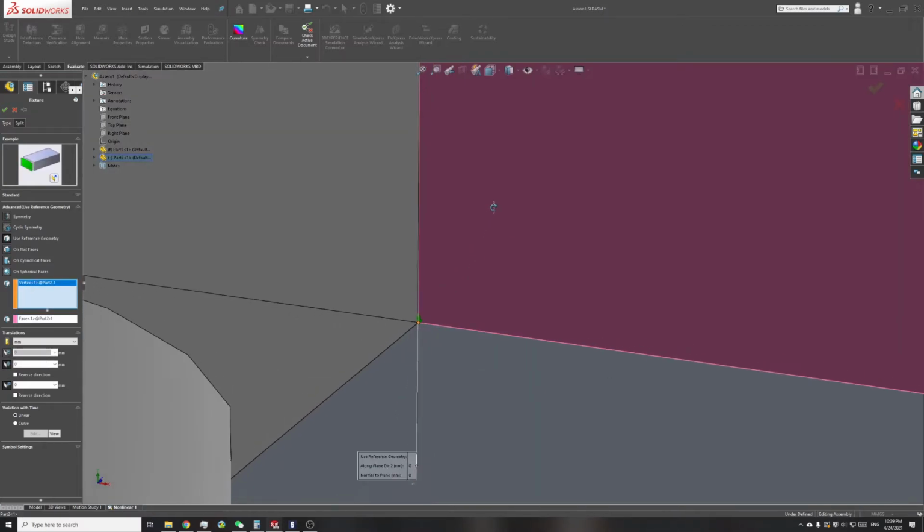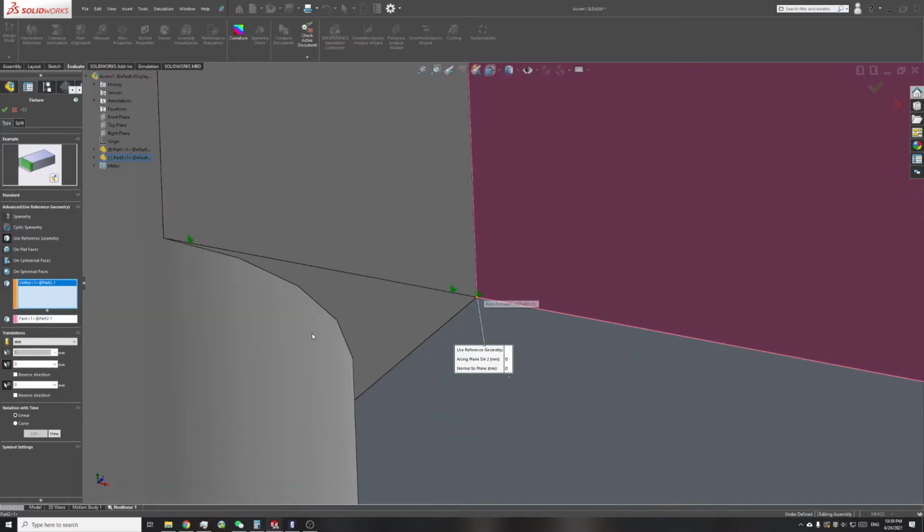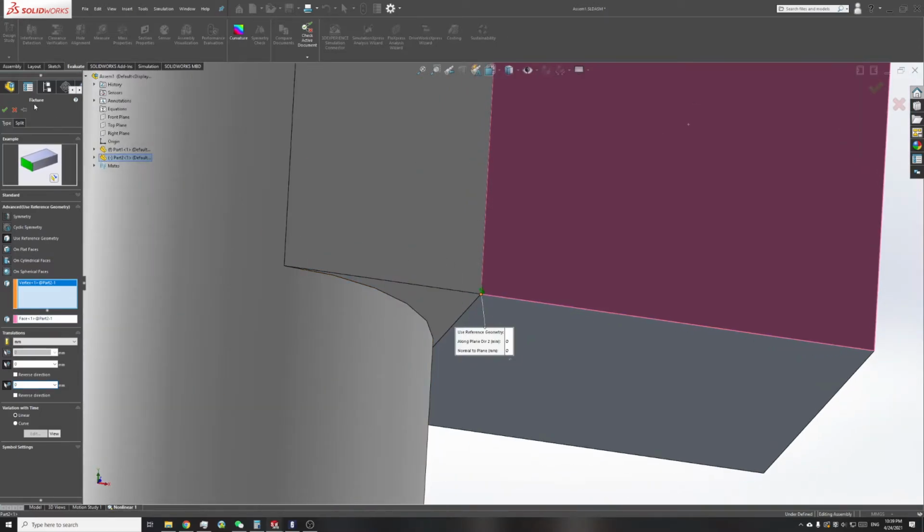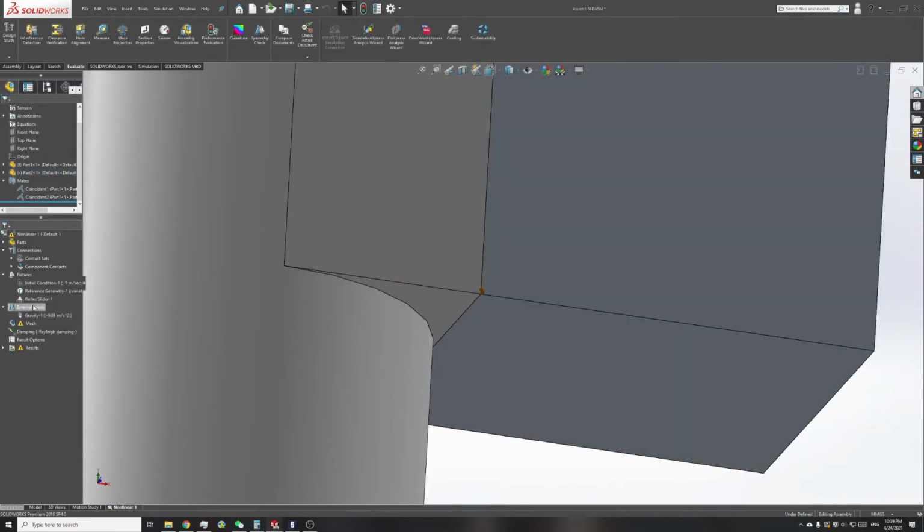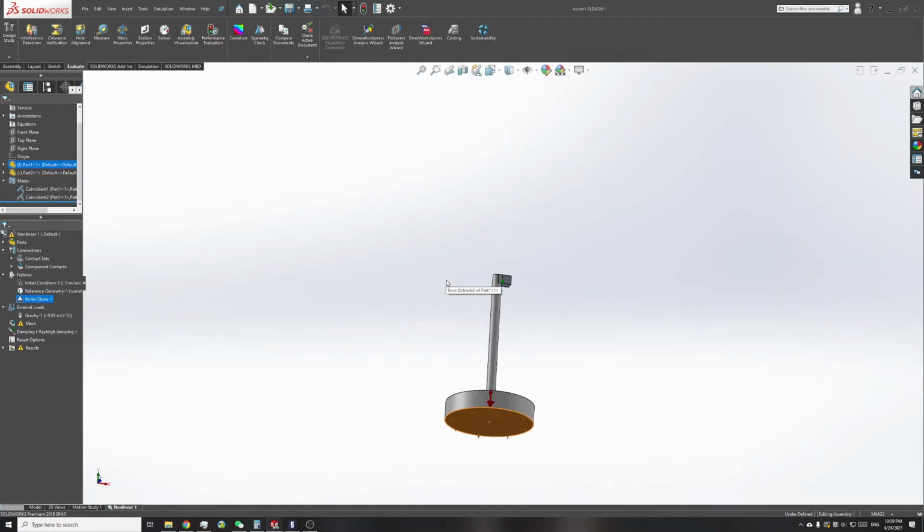You get 4 arrows, which means that it allows movement in a direction by a certain amount. So you put 0, which means you don't allow it to move in that direction. Also 0 here, which means it only moves in this direction, which is along the line of punching. Right, so a roller slider.